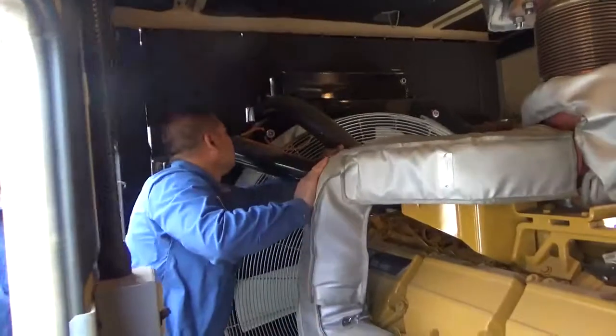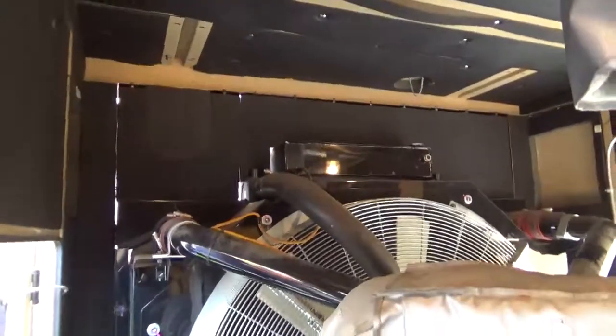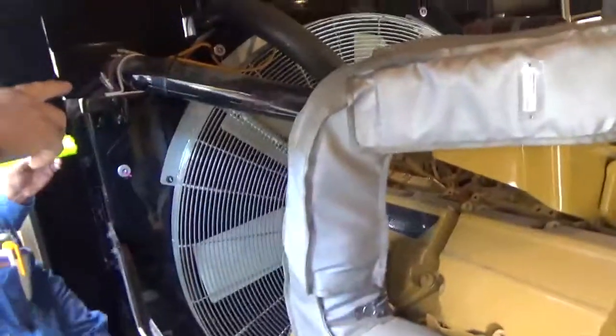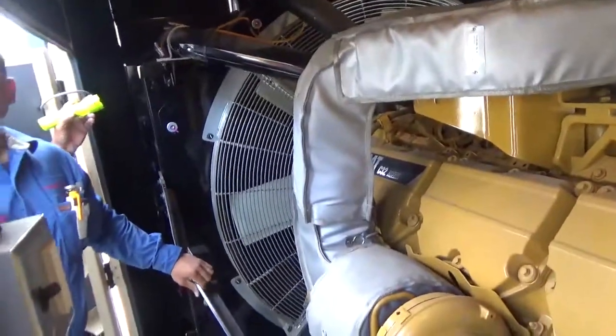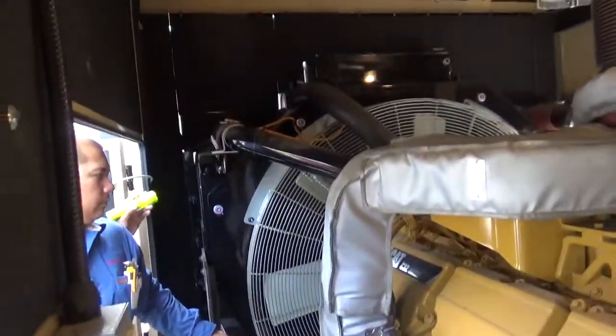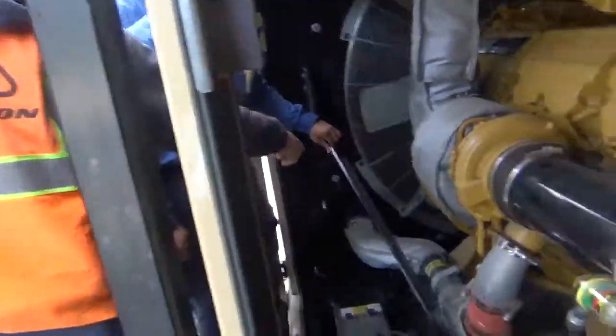It's what they call an air-to-air aftercooler. So it uses outside air to cool the combustion air, basically. The big black pipe there and the black pipe here are air. Obviously the hose is the water. The first radiator core is your aftercooler core, and in front of that is the radiator core. Water drain down there on the bottom.